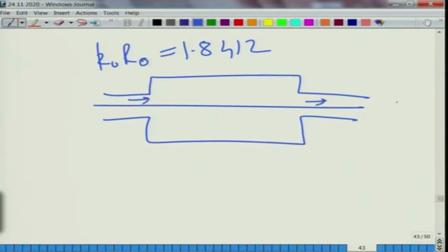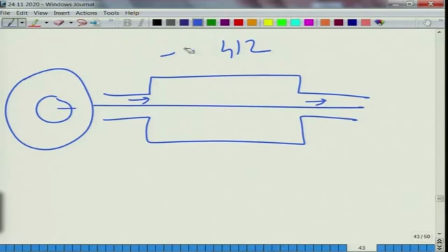So, this is all coaxial or concentric. For such a thing, azimuthal or circumferential modes will not propagate, only the radial modes propagate, and the first radial mode occurs at the frequency 3.83 or something like that, if I am not wrong, for a circular chamber. So, we can work out that, and we are seeing the non-dimensional frequency axis.